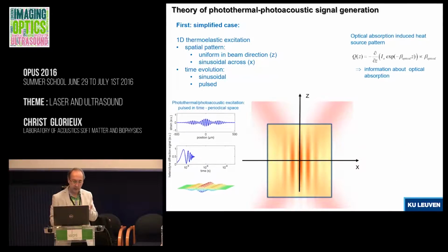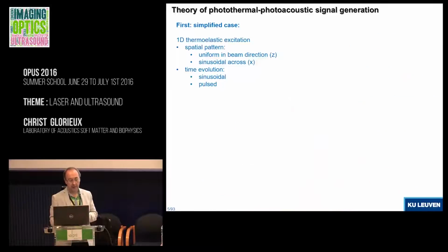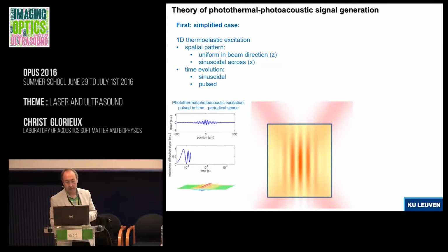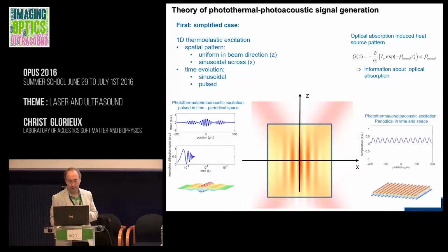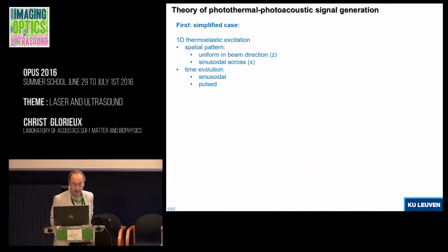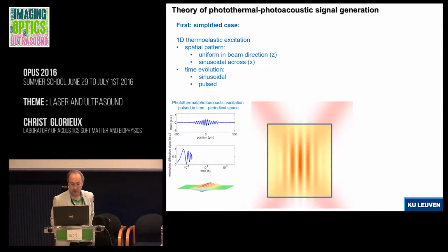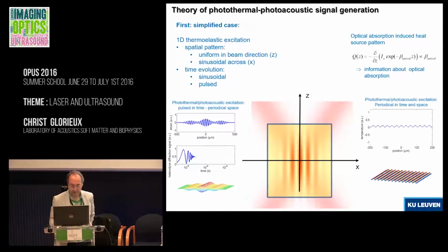Actually the three. They have the optical absorption, they have thermal expansion, they have acoustic waves, and at the end, if you wait long enough, because it's a bit slow, you also have thermal diffusion. So a lot of information in one signal, and you even have acoustic attenuation, so all is there, and you can do really material science.